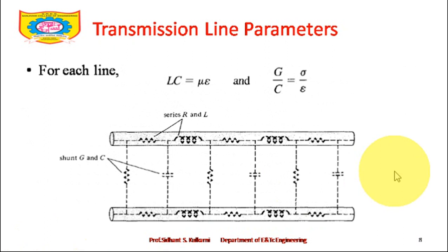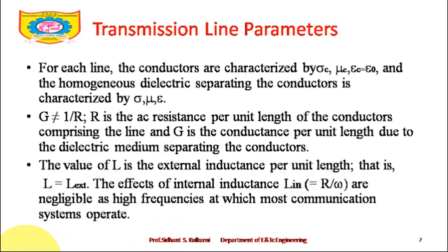to the conclusion, as I had told you, that the parameters of the transmission line in terms of resistance, conductance, inductance and capacitance are distributed over the line. They are not lumped ones. So the field theory approach should be used in this case instead of the circuit theory approach. We talked about that in the previous lecture. Let's talk about those things.